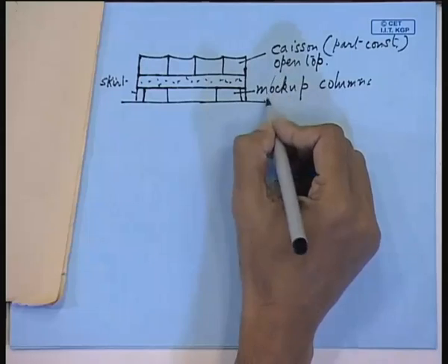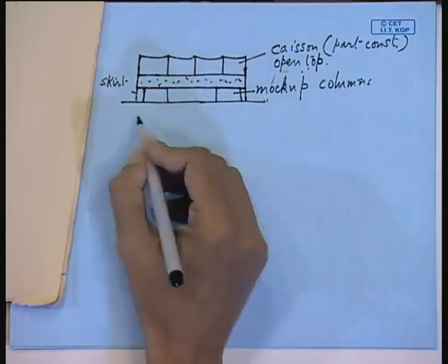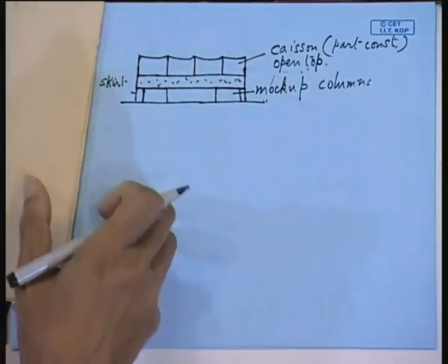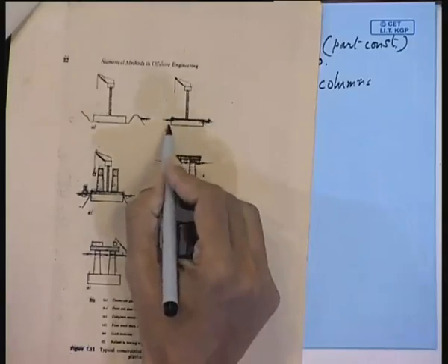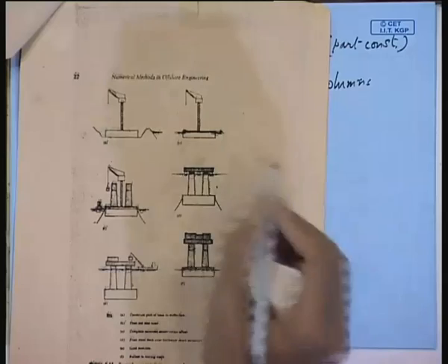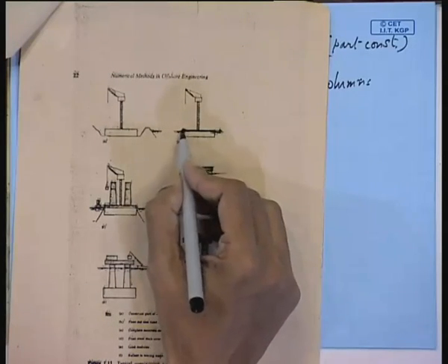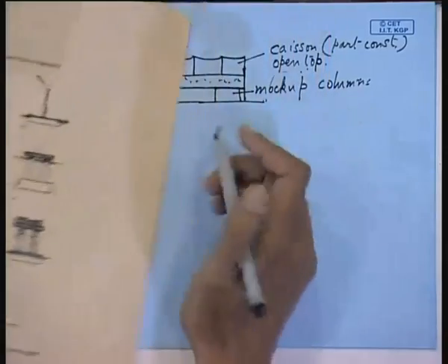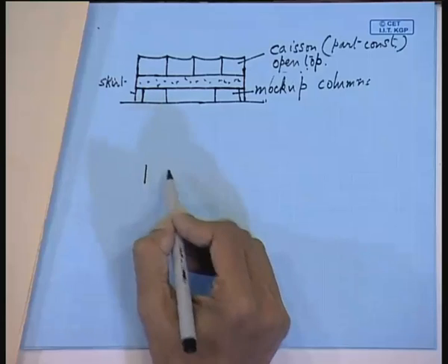Now, after this is made, then you remove your embankment and float out. The whole structure is floated out, as you can see here. So this is the part of the structure that is shown here. That means in a smaller diagram you can see this base slab, a part of the pontoons, but it still has this open caisson. Caisson is open.